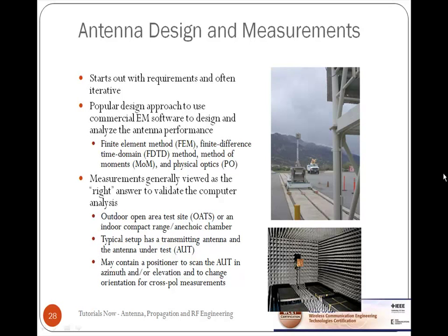And some of the commercial EM software are based on methods such as finite element method, or FEM, finite difference time domain method, or FDTD, the method of moments, or MOM, and physical optics. However, measurements are generally viewed as the right answer to validate the computer analysis, and one can resort to outdoor open area test site, or OATS, or an indoor compact range and anechoic chambers.